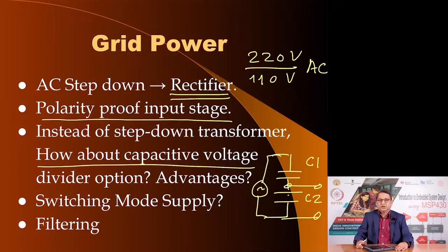Another option, and it is a very common approach, is to use a switching mode power supply. This switching mode power supply, which is being used in phone and portable device chargers, comes without the weight and bulkiness of a traditional step down transformer. What it does is it takes the AC voltage and rectifies it right away.